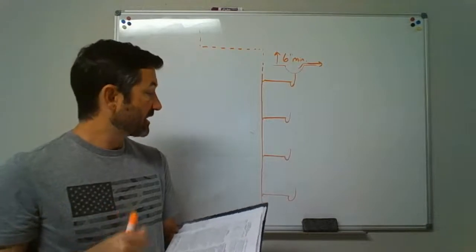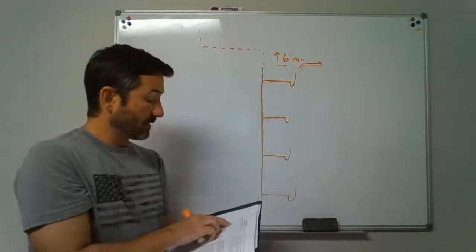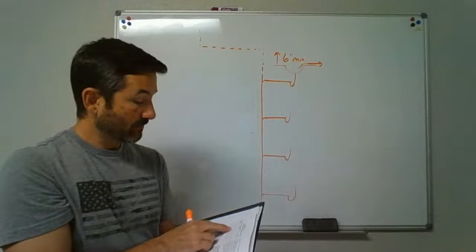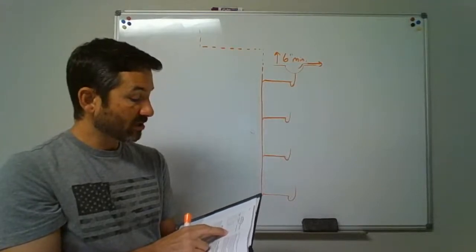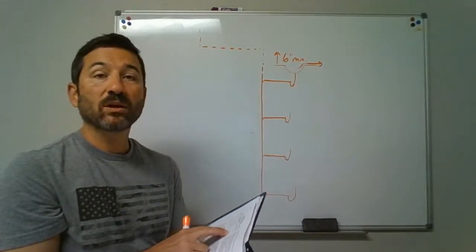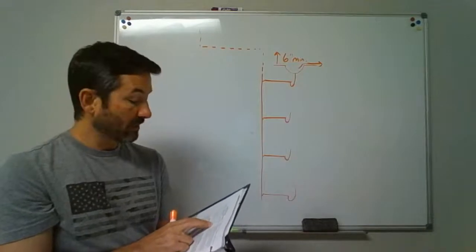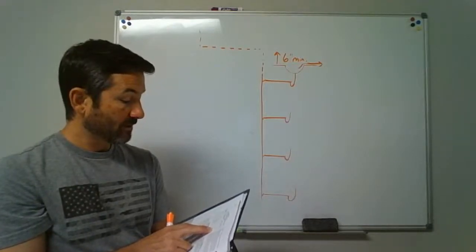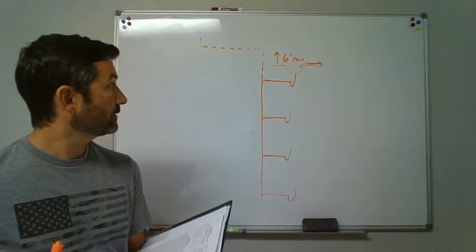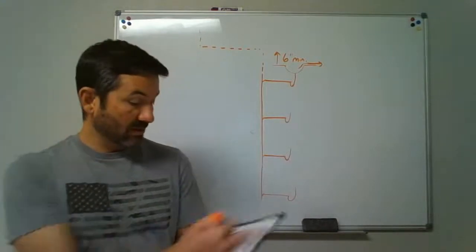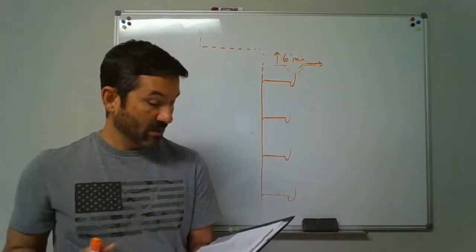So if you said, how about if we plumbed a 3-inch stack up? How many DFUs could that handle? Well, the total discharge for the stack is going to be 24 DFUs for a 3-inch stack. Okay, so you can kind of see how that's sizing out.